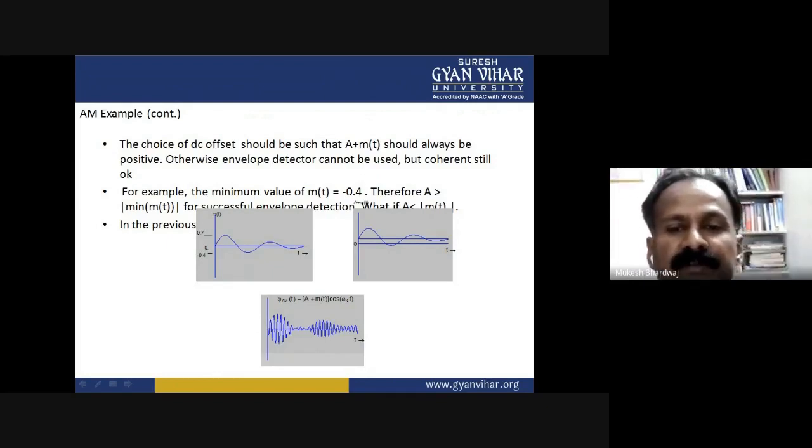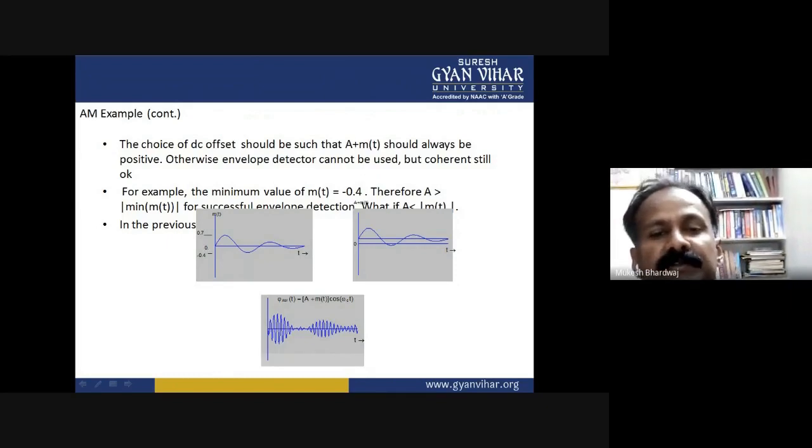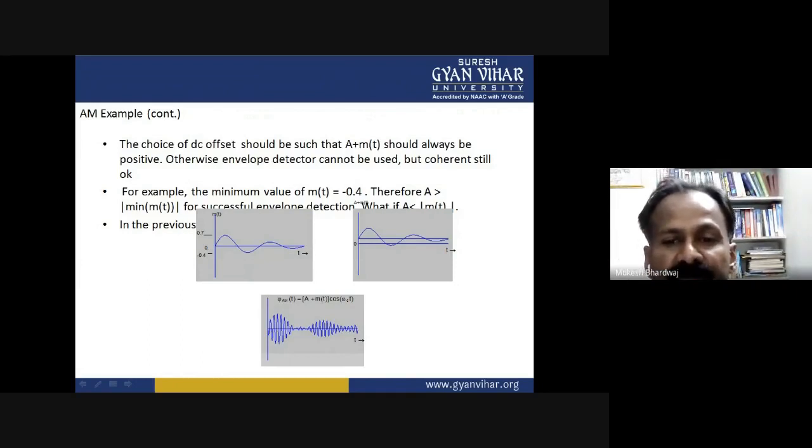Modulation, therefore, is the fundamental requirement of a communication system. Modulation may be defined as the process by which some characteristic of a signal known as the carrier is varied according to the instantaneous value of another signal, known as the modulating signal. The signals containing the intelligence or information to be transmitted are modulating signals. These modulating signals containing the information are also called baseband signals.